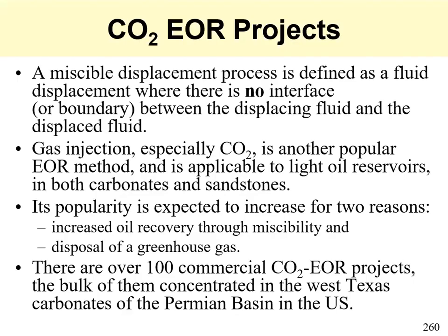So let's go into miscible gas injection or gas flooding. Remember that the conventional screening tables have been presented earlier. So a miscible gas displacement process is defined as a fluid displacement where there is no interface between the displacing fluid and the displaced fluid. This is a clear contrast to immiscible displacement, especially for gas immiscible displacement.